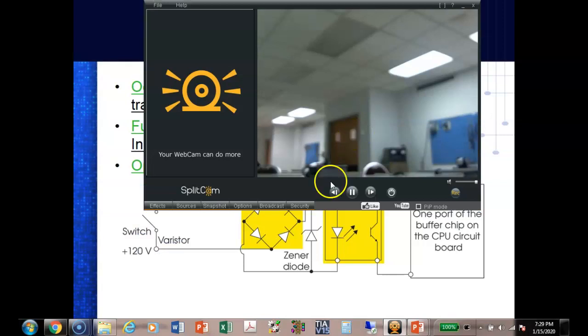I'm not touching that projector up there, but I'm able to pass information through it, and we're isolated from each other. So all this garbage that's in the outside world, we can filter that out. We can convert AC to DC, have 120 volts over here and 5 volts over here, because we're coupling the information through this optical isolator. That makes sense? And this is on all of them. Not only is it on the input ports, it's also on the output ports.